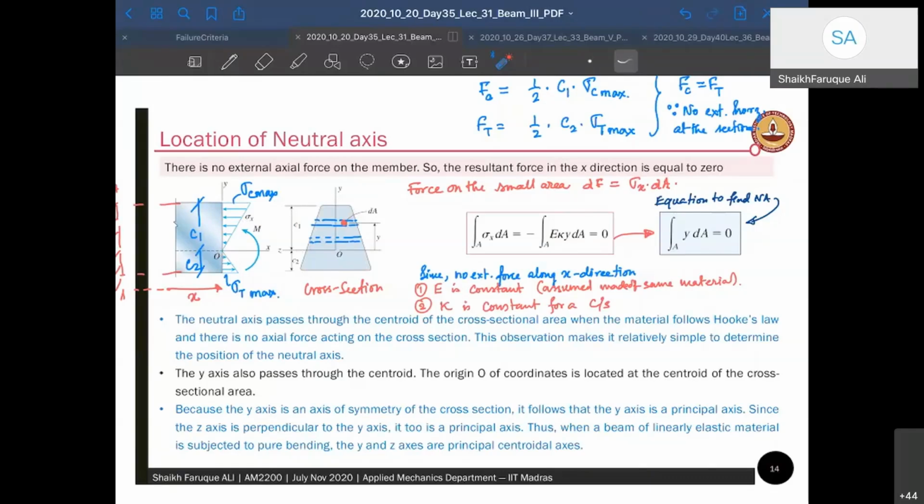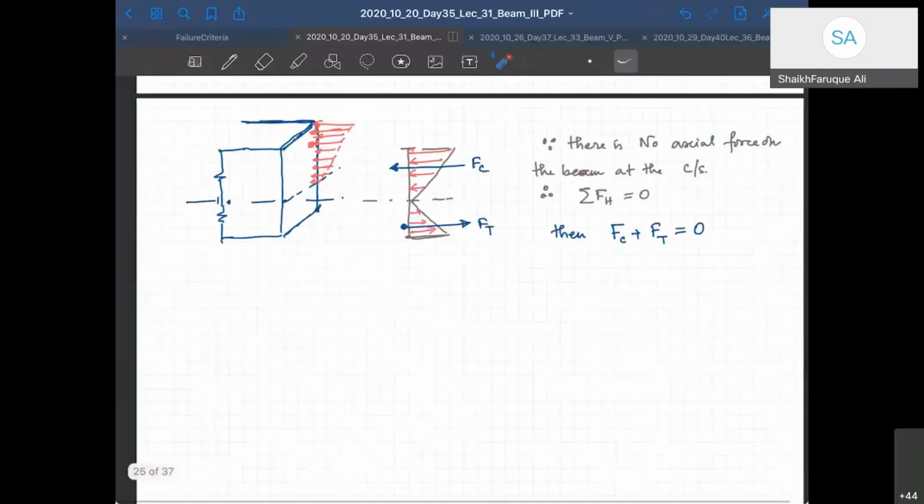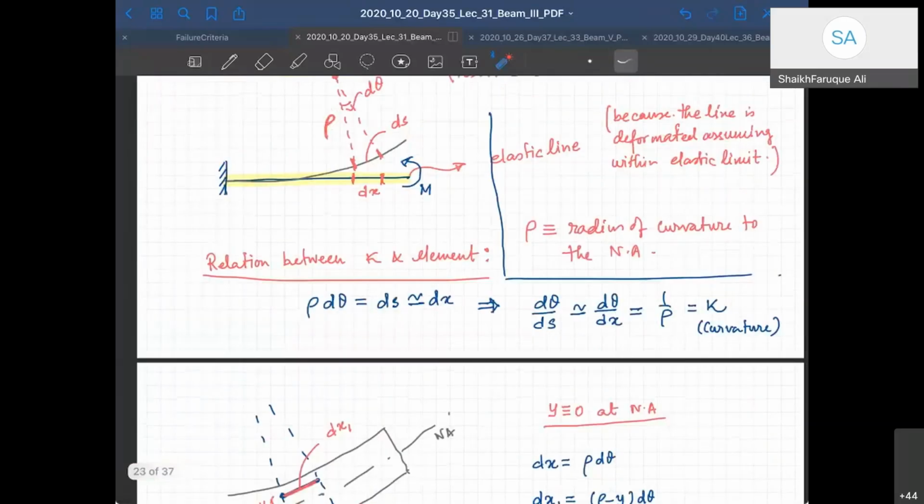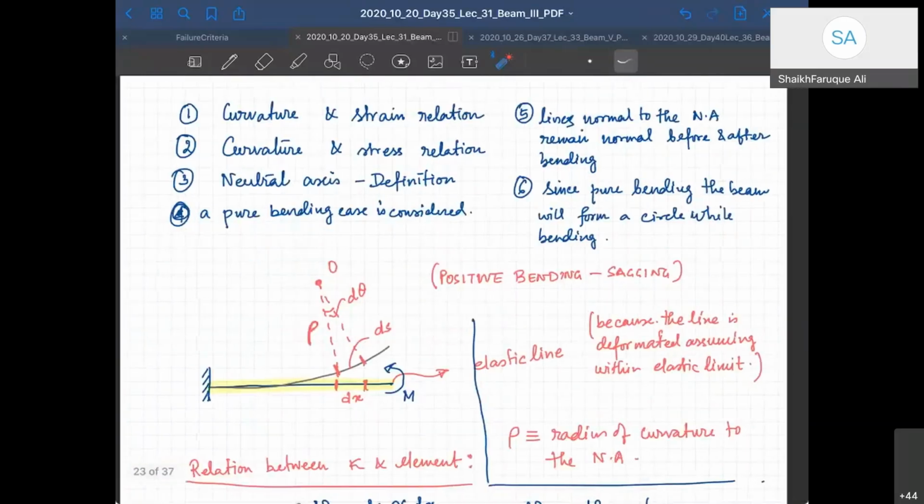Moment can change with time, moment can change with loading also, right? For example, I gave only one moment here, on one side of this beam. If I give another moment here, the curvature will change. Curvature will be like this and then this. Yes, sir, but even then we will be calculating for the given moment. Not for a given moment. You have to calculate based on the bending moment in the beam structure.